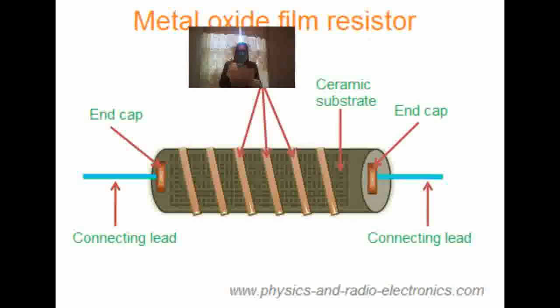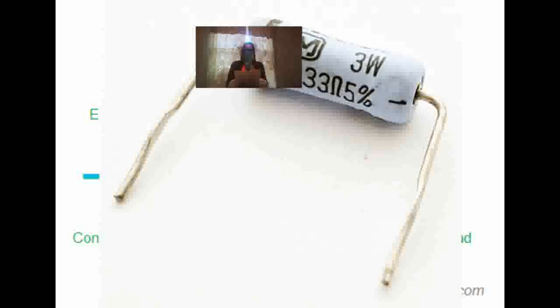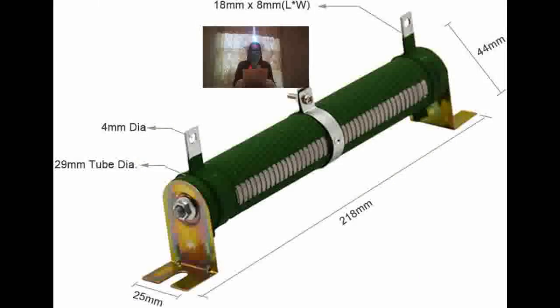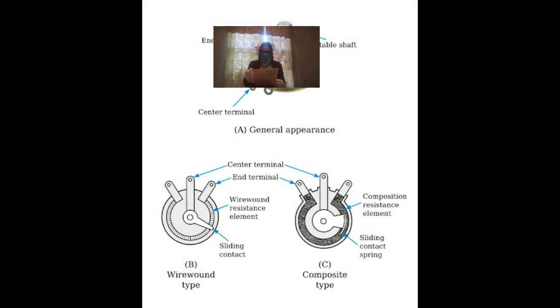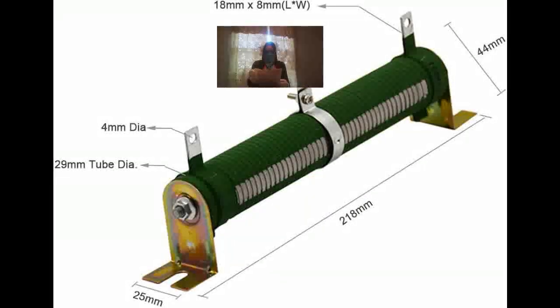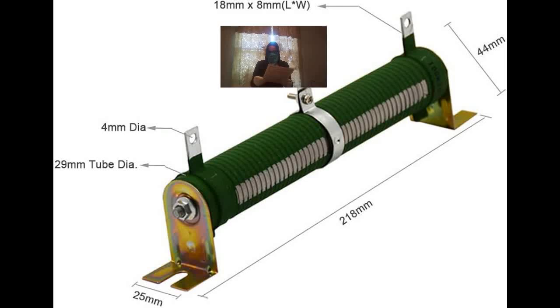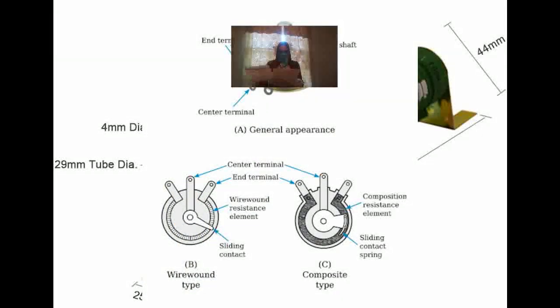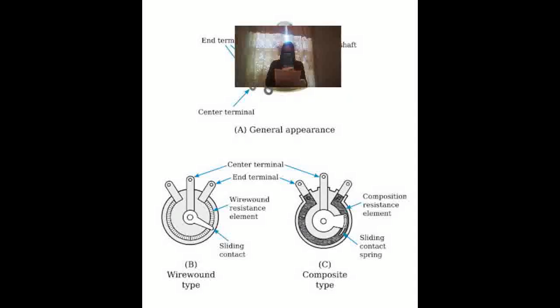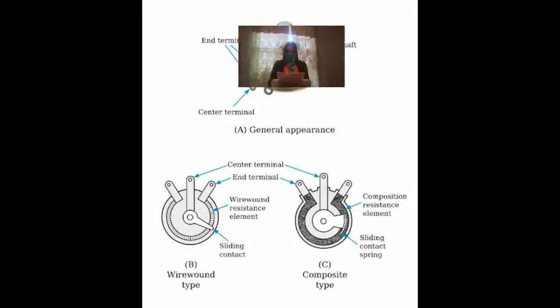Metal oxide resistors are also used for high voltage and wattage requirements. Another type of wire-wound resistor is the adjustable resistor. Unlike the standard wire-wound resistor, the adjustable resistor is not entirely covered by enamel material. Instead, a portion, an adjustable sliding tab, is attached to move across the exposed surface. This allows the resistance value to be varied. The adjustable resistors may have 2 or more taps for providing various resistance values in the same circuit. An adjustable resistor and the symbol are shown in figure 3-34. Potentiometer. Most electronic equipment requires the use of variable resistance parts.